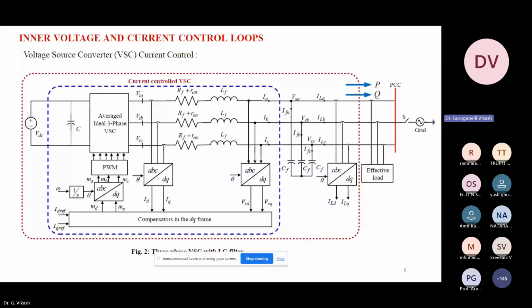That's it. But in case of islanding mode, we don't know the load. Based on the load, the inverter should provide that power to the load. So that is the difference between islanding and grid connected. Actually in India, most of the inverters are grid following.